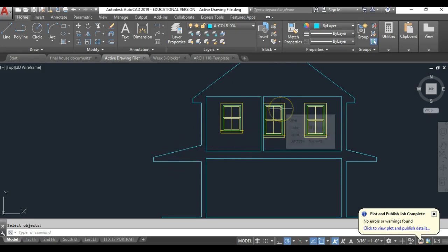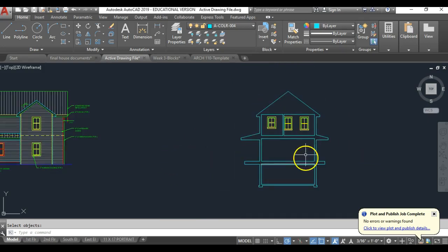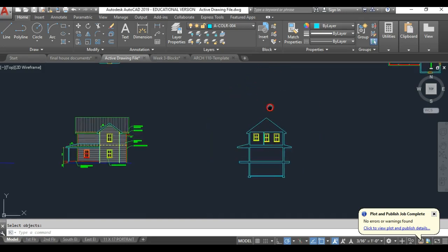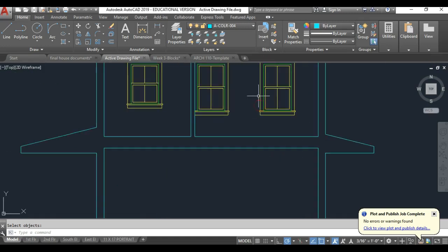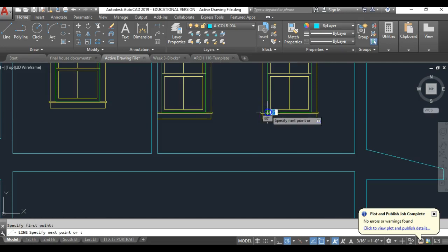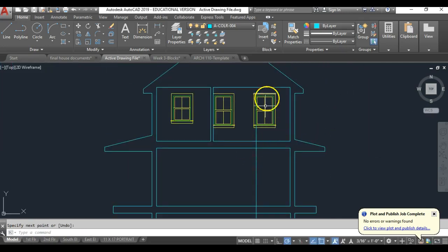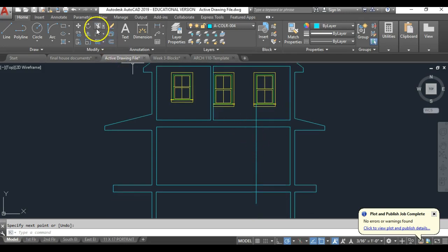So there is this window. If we recall, the window that's down here is above the kitchen, so it had the same sill height and same width and same head height as this. So we'll use this as a model to place our window down in here. In fact, it's aligned purposely with the window above. So I know A, that it comes down here. I know B, that it has the same head height, which is 7 feet, so I can offset 7 feet, or I could have done it graphically from across my drawing.